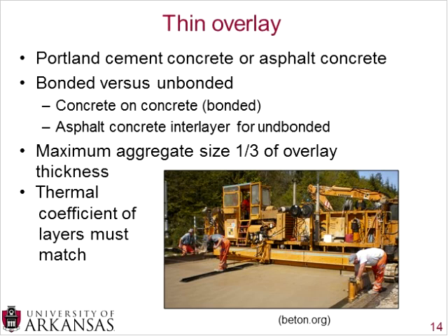So pavements do expand and contract when the temperature changes, and you want to make sure that these layers you're putting together expand and contract the same distances, the same amount. Because if they expand and contract to different sizes, then there will be problems with that interface area. So perhaps the bottom will expand a little more than the top, and you'll have uneven joints, and that's a very bad quality for pavements. So you want to make sure that they shrink and expand at the same rate.